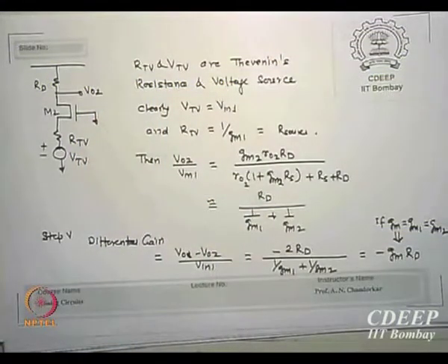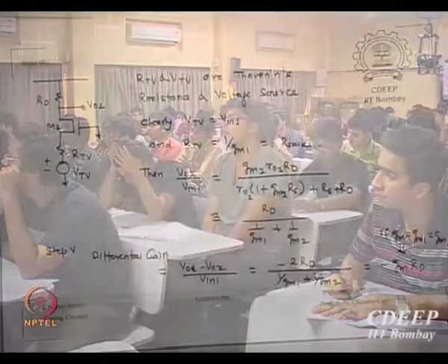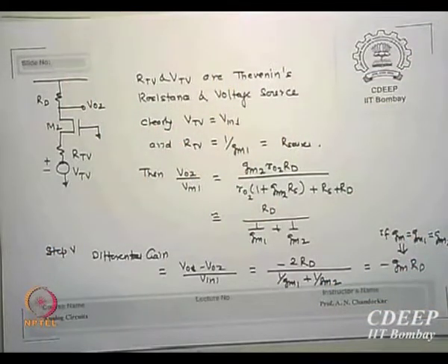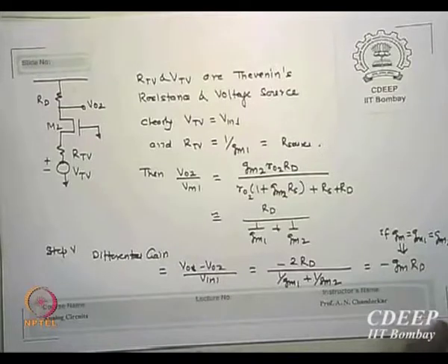Okay. Can we say now same thing can be repeated for Vin2? Identical situations. Okay. So how much we can get for that? VO2 minus VO1 will be similar value. Okay. And then the net gain will be how much? Subtract करोगे तो 2 GM RD will be the gain of a difference amplifier. Calculate VO2 by VO1 or VO1 minus VO2 by the same technique for the other arm now. Okay, इसको ground करो, इसको वो का वही, यही gain वापस आ जाएगा. Add करेंगे तो it will become 2 GM RD.